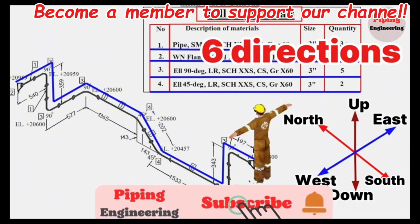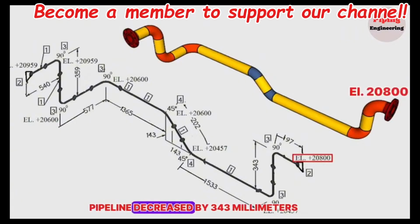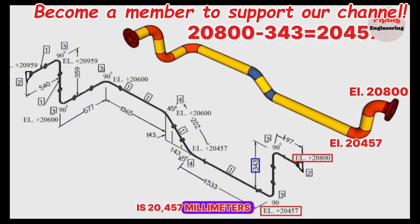Now, let's learn the elevations shown in the piping isometric drawing. As you can see, the elevation of the starting point of the pipeline is 20,800 millimeters. Here the level of the pipeline decreased by 343 millimeters vertically and became 20,457. We can easily check the correctness of this elevation. 20,800 minus 343 equals 20,457 millimeters.